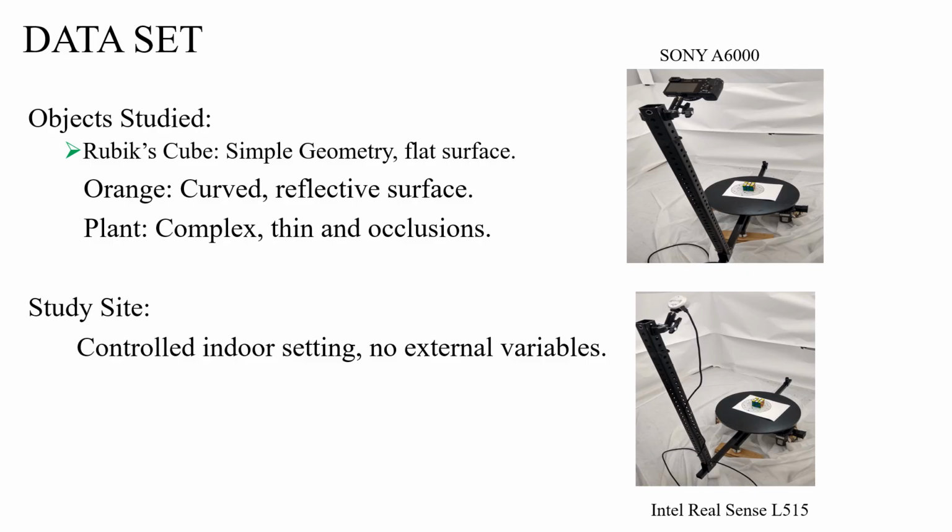These methods are performed at 10 rpm and 30 rpm. At 10 rpm, nearly 160 images were collected, and at 30 rpm, about 78 images. At speeds above 30 rpm, the images had less than 50% overlap, which leads to misaligned point clouds.